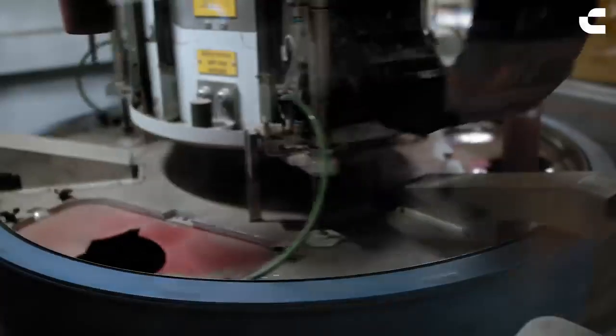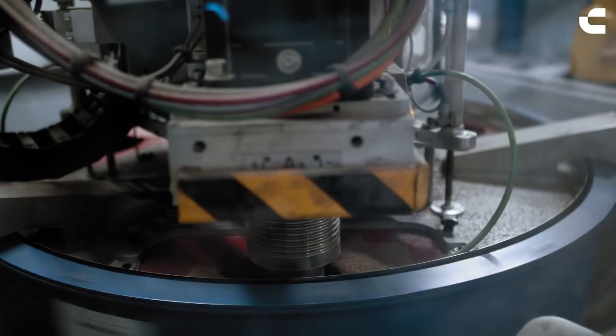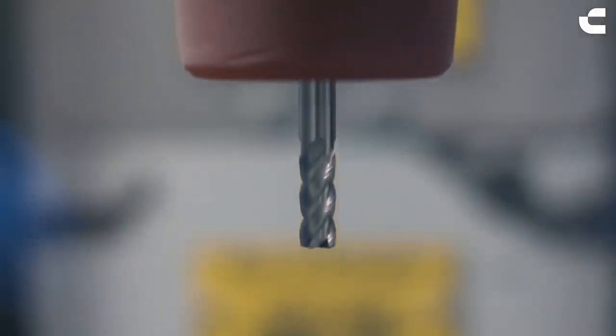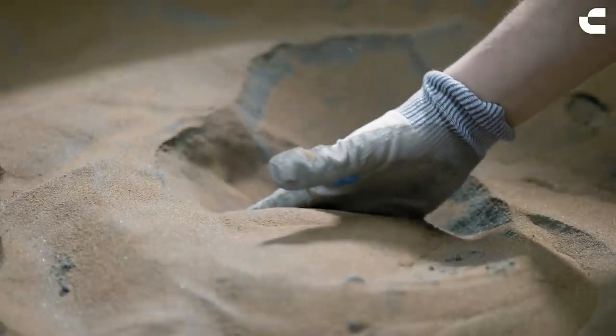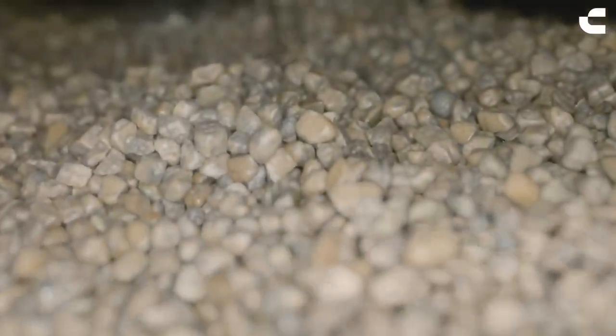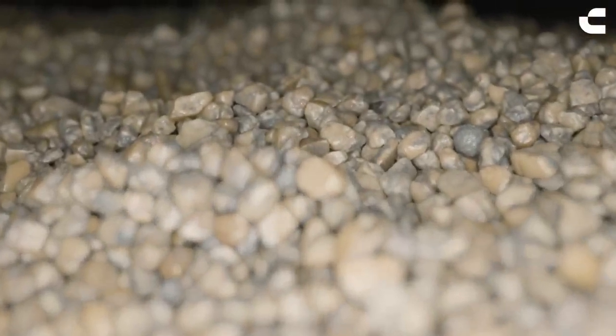This is achieved by dipping the tool into a rotating drum filled with fine-grained sand. For this process we use a special sand which is based on aluminum oxide. The value of roundness that you need to achieve could be 4 microns, 5, 8 microns, and depending on the quality of the edges we use different media, from raw to really fine and finishing media.